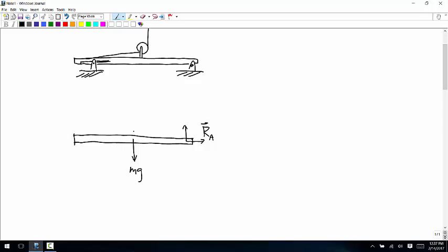And now we get to the pulley. You can approach this a few ways. One possibility is that you don't include the pulley in your free body diagram. If you don't include the pulley, what is the type of joint between that part of the pulley and the beam?